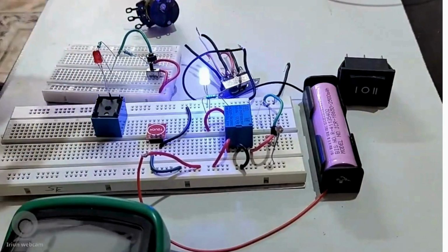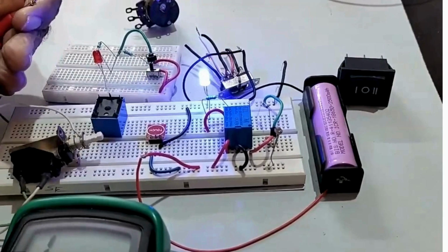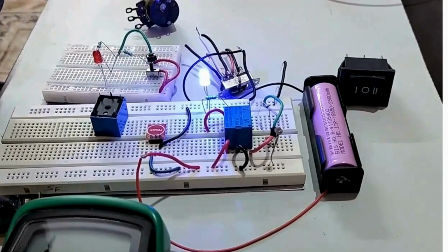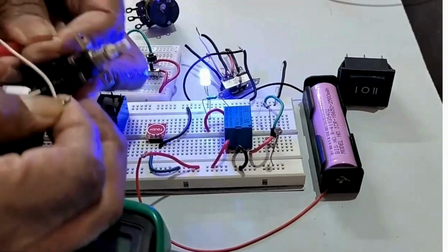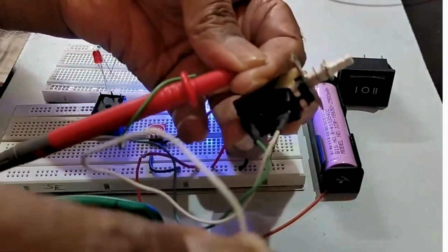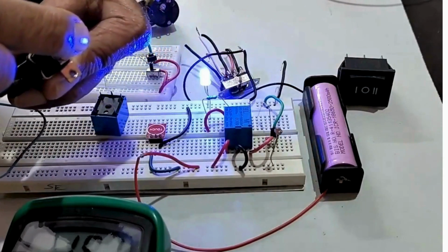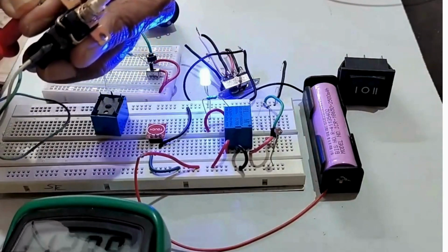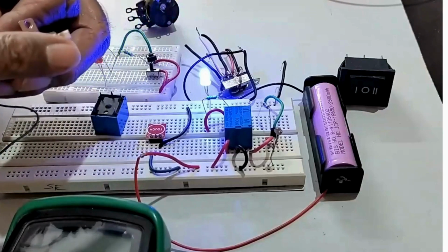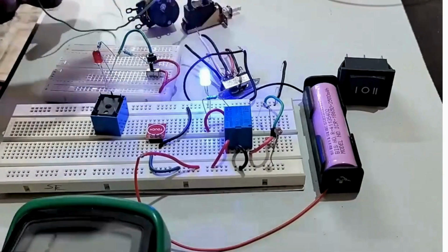I'm connecting it. I've connected the buzzer mode. You can see these 2 wires, I've connected them with my 2 hands, and when I press this, you can see some resistance has come. This is continuity mode. I'm removing it, it goes to the normal position. If the switch is working, it will show continuity. If the switch is not working, it will not show continuity. So this is the way you check switches.